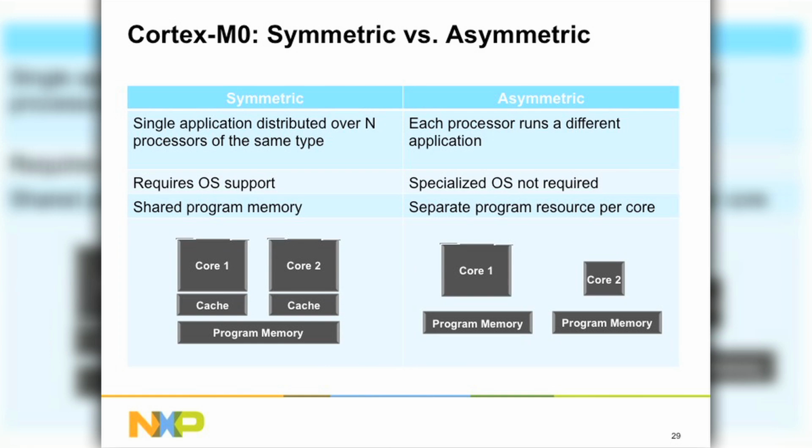But let's think about signal processing in DSP. If you've ever programmed real-time DSP, you can't be away too long from waiting for that next interrupt to come in because you've got to service it, you've got to do your filter, et cetera. If you're off servicing a USB routine or Ethernet routine, you're getting a lot of interrupts, your system becomes much more complicated. So we said, well, we've got the capability. We have the M0 in our portfolio. We have the M4. The M0 is a very small gate count compared to all the other things we have in the chip, very small gate count. And we have the knowledge to know where to put it and make it run fast. So we said, let's put it on there.